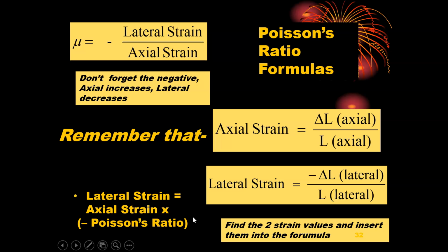Okay, so what is the deformation in X and Z when a piece of magnesium is 25 inches long and has a 0.75 by 0.500 rectangle end and stretches 0.5? First, we find the axial strain. So the axial deformation divided by the original length. I said that it stretched 0.5 of an inch, so we'll take the strain, the change in length divided by the length, and we say 0.5 divided by 25, and that equals 0.020.